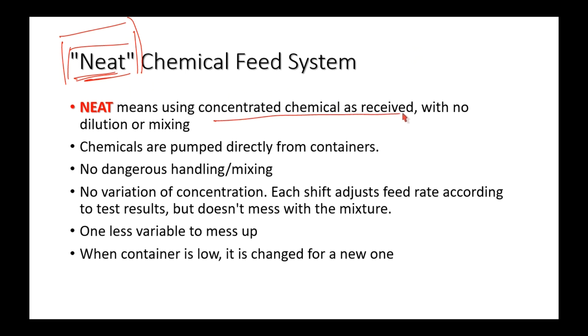So we add the concentrated chemical as received, no dilution, no mixing. We pump directly from the container. And the cool thing is we don't have to handle the chemical. We don't have to mix it. We're not going to get splashed with it. Yeah, we're going to wear our PPE. We're going to wear our aprons, our gloves, and our face shields and stuff like that. But less chance of having the stuff land on your skin or getting in your eyes.